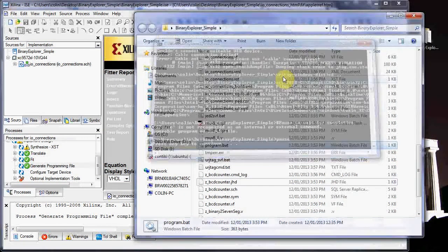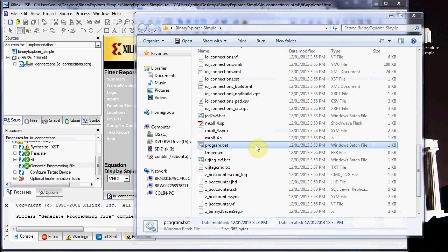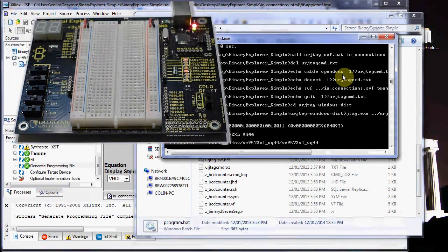Oops. In this case, it doesn't seem to solve it. Try this a third time. If that happens, you can also try switching what USB port it's connected to. It could just be an issue with one port of your computer. Sometimes if a board is giving you too many errors, it will actually disable that port. So it can help to connect it to a different USB port. There we go. I connected to a different port, and this time it worked. It can take a bit of playing around occasionally, but for the most part it works quite well.